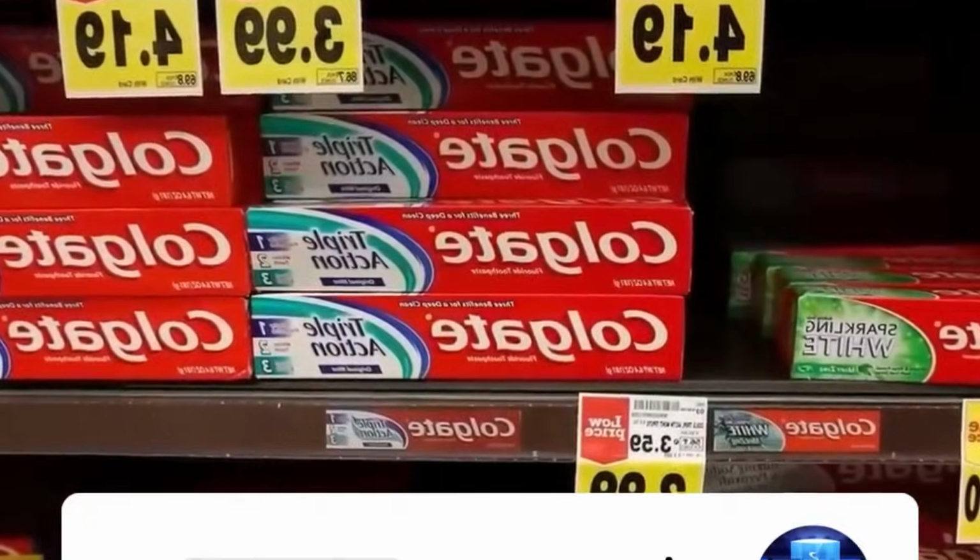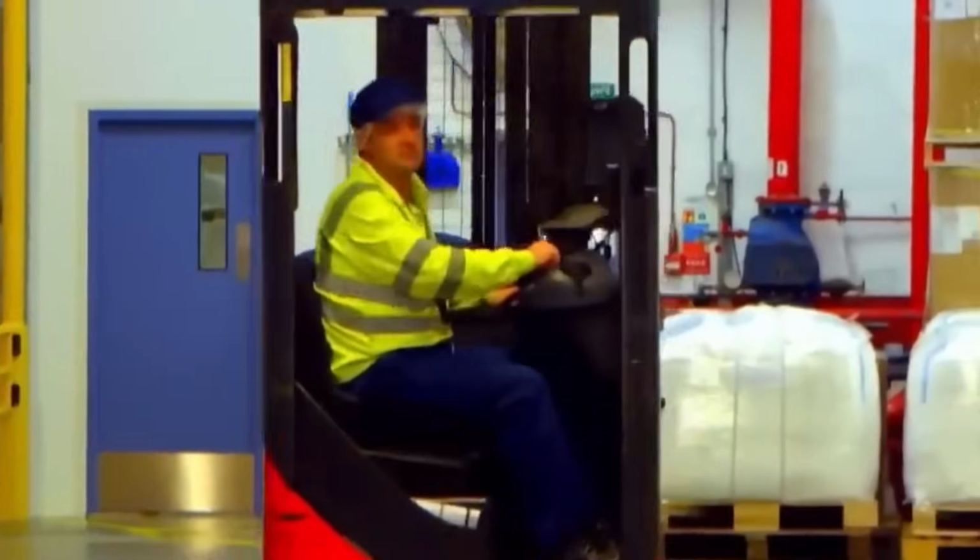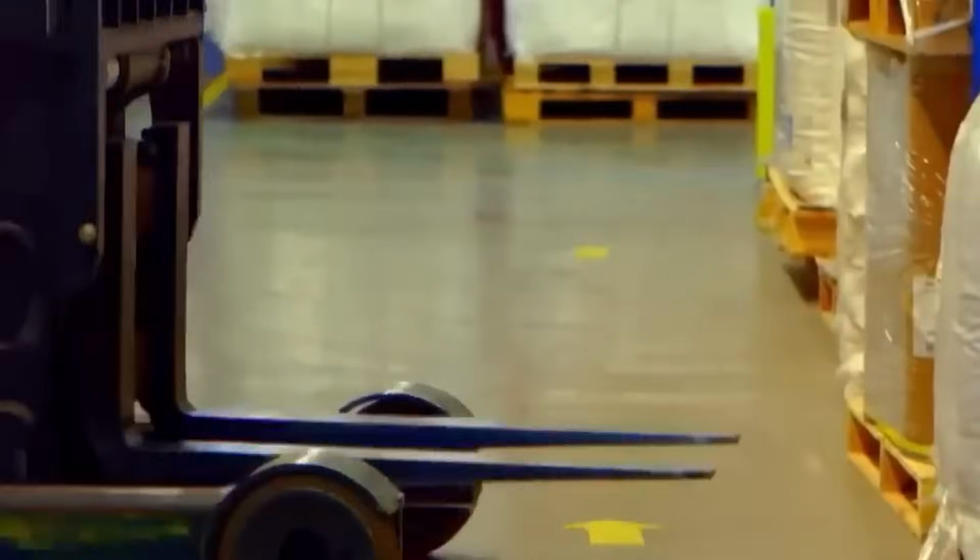Toothpaste production begins with the batching of raw materials into three primary categories: abrasives, humectants, and active ingredients. These components are stored in bulk silos, intermediate bulk containers, and stainless steel drums positioned adjacent to the central mixing facility. Ingredient delivery is managed through automated vacuum conveyors, liquid transfer pumps, and weigh-scale monitored feeders.